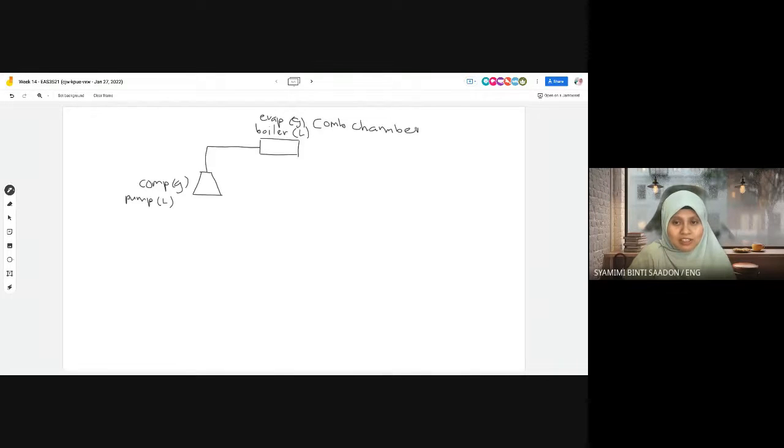So you have to understand this. The different component depends on the function, depends on the working fluid. The combustion chamber is for an aircraft engine or jet engine, an open cycle. Mainly this part is where, other than increasing temperature and pressure, the device, evaporator, boiler, combustion chamber, exchanges heat. So that's why it is called a heat exchanger. These three are types of heat exchanger.